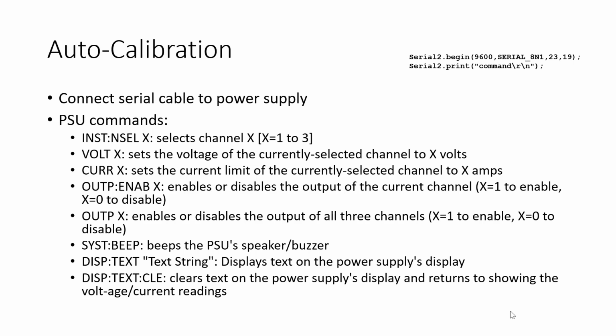So you can actually plug these into the power supply if you take the screws off. If you get a nut driver. Exactly. But the problem is the connector's in the back, right? Yeah, it's in the back. It's a little annoying. It's easier to use a cable for sure. So we bought the cable. So Alex gave you all cable. So you need the serial cable and you need the banana clip, alligator clip cable. So one of the cables goes in the back of the power supply and the other one goes in the front.